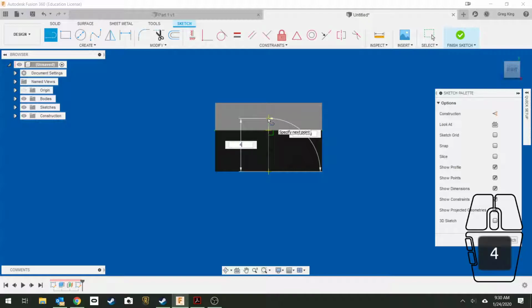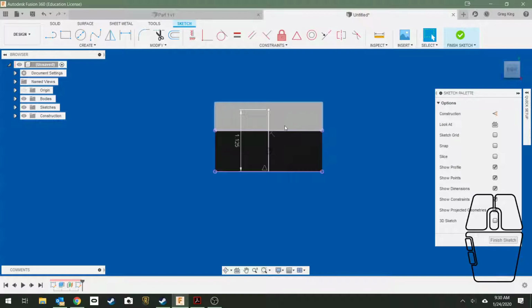So it's 4.5 fourths, and that's a dumb number, but it works, and Fusion 360 can use it, so I'm going to use it. 4.5 fourths up. So now, once I have that line as a reference, I can use that for everything else because it helps me to lay out my pieces of this building, which are otherwise a little hard to do if you don't have to do measurements from the sides and everything. I can work from the center point.